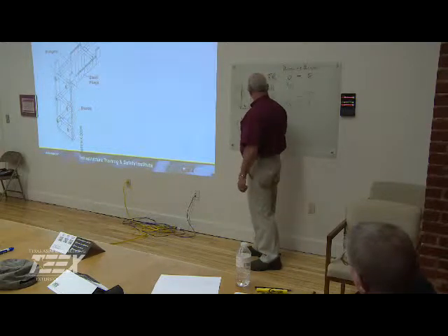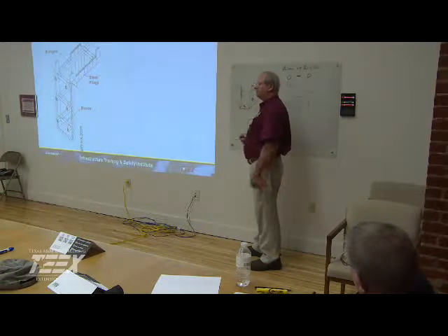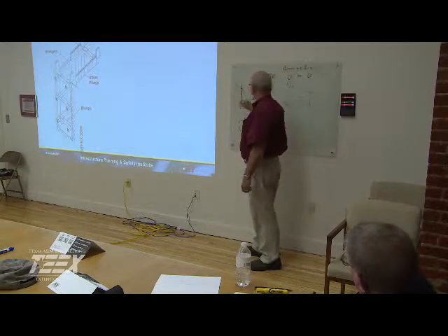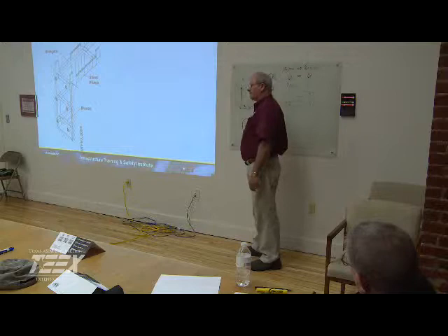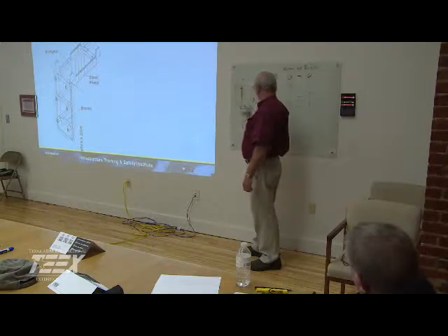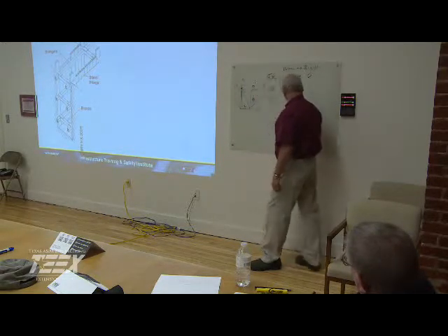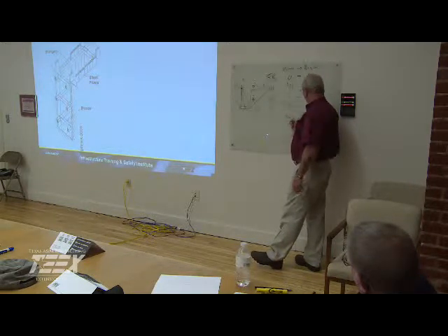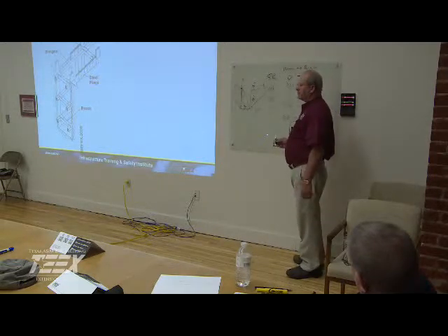They must be within 25 feet of all personnel. And it must be tied off, it must be secured, and extend at least 3 feet above the rim. Okay? And this is for any trench that is 20 feet or less. Anything that's greater than 20 feet, then you have to have an engineer design the safety device.